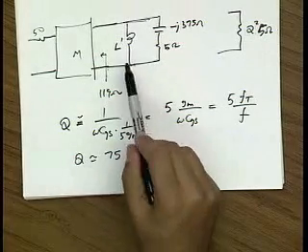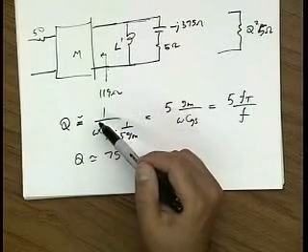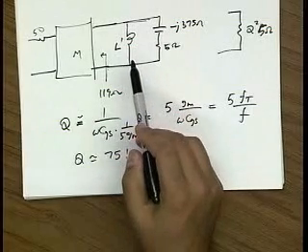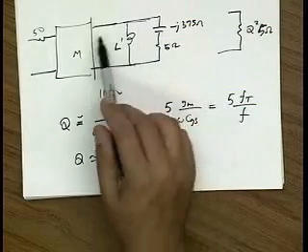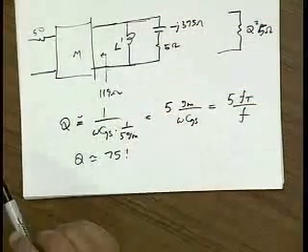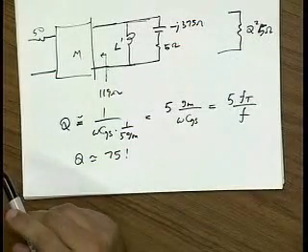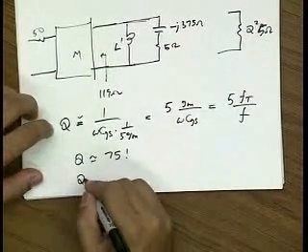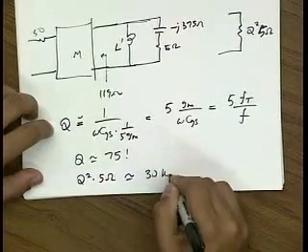First of all, you're not going to be able to find an inductor that has a Q better than 75, even if you go buy the most expensive inductors you can. So really what's going to happen is when you put this inductor down, you're going to add a lot of resistance in parallel, which is just basically increasing your noise figure. But also now notice that Q squared times 5 ohms is something like 30 kilo ohms.